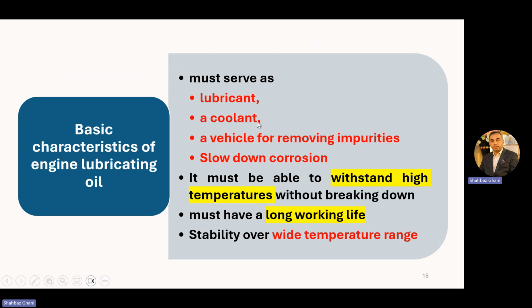Second, a coolant. So the primary task is to act as a lubricant, and the secondary task is to act as a coolant. And it must serve as a vehicle for removing impurities. All the metal parts which are moving, there is some wear going on. So it extracts those impurities with the oil and carries them back to the filter or the sump.